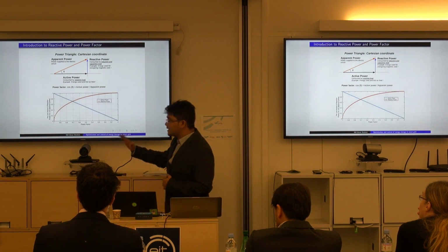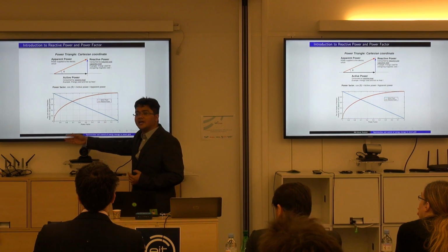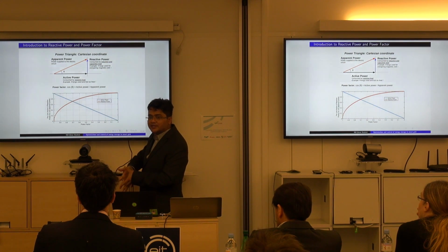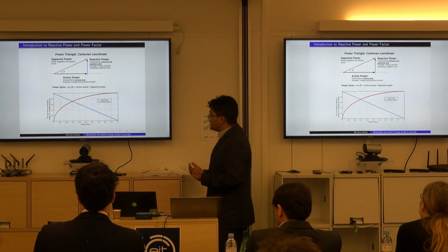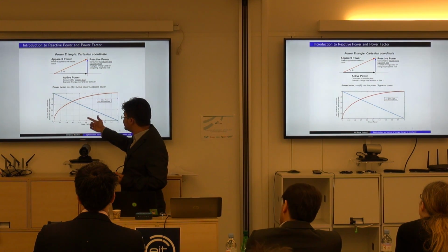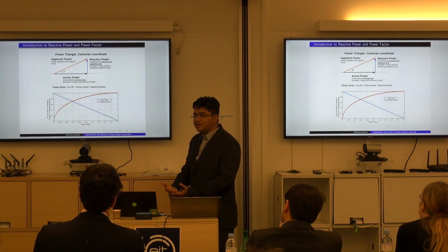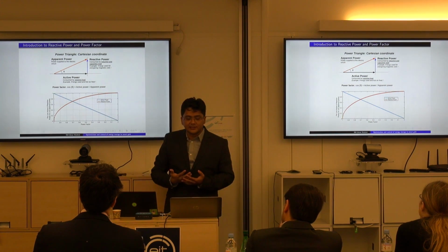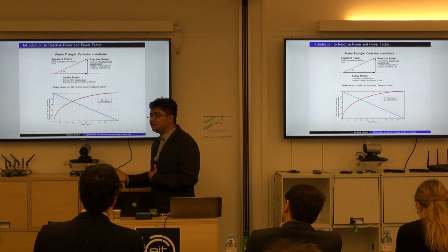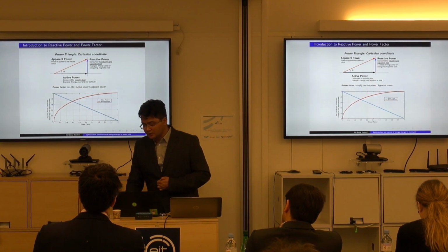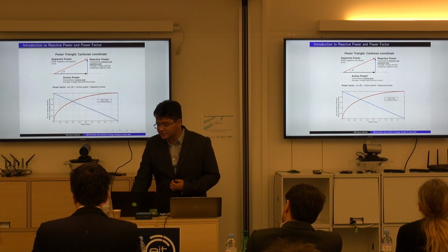Suppose for a cable which has unit amount of apparent power carrying capacity, as my power factor deteriorates, which implies that my reactive power is occupying most of the space in my cable, and my active power carrying capacity is linearly decreasing. What it means is, suppose for a utility, a low voltage consumer operating at say 0.5 power factor will consume a lot more reactive energy, which is not even billed, and so it's essential that consumers maintain power factor. However, that was not very crucial because power factor typically for low voltage consumers was close to 0.9 or higher. But now I'll demonstrate using a case study that power factor degradation is a real problem which can happen because of DGs in future.